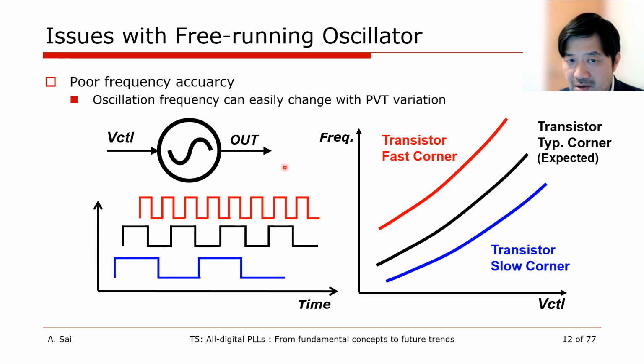In order to accurately down convert wireless communication, it's necessary to match the local frequency with a desired channel at a very high accurate level. Free running VCO have large frequency fluctuation due to the transistor process fluctuation or variation and I think metal wiring parasitic variation.